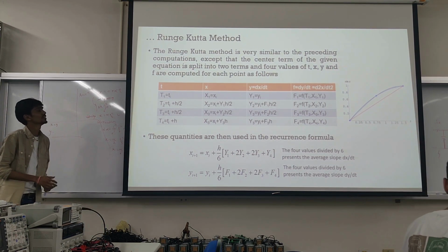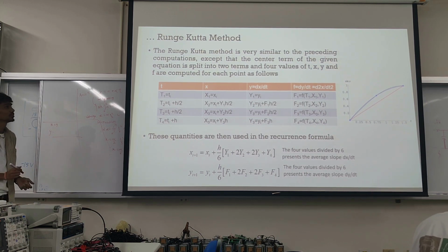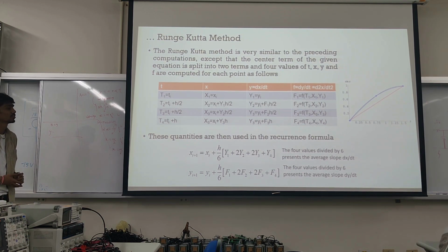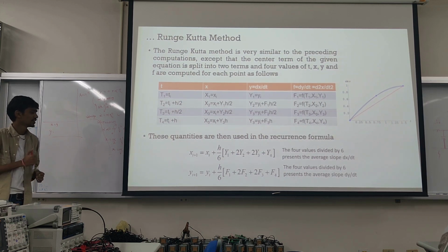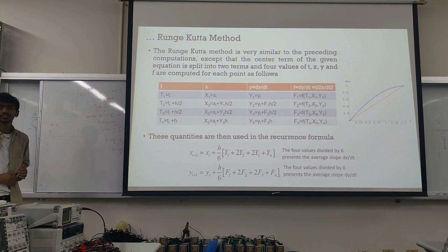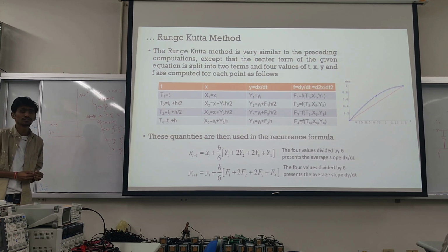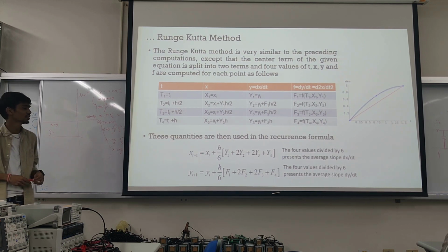So last time we discussed this Runge-Kutta formula method. From this formula we are going to calculate the displacement and velocity, and this displacement and velocity we are going to plot, displacement versus time and velocity versus time, in Matlab.